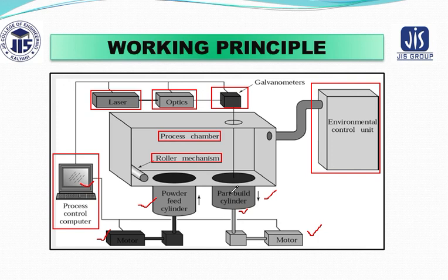Next, we are talking about the part building cylinder, which is lowered incrementally. So, just think: this one is raised slowly, and this part build cylinder is lowered slowly. One is raising, another is lowering, to where the sintered part is going to be formed.